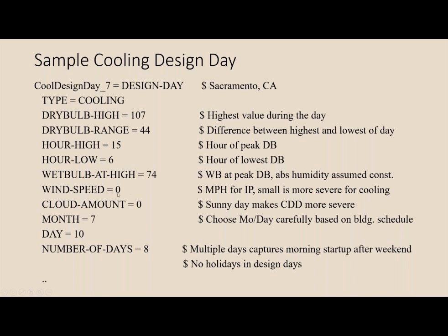I had a fairly high wind speed in my design day, and I discovered that during the design calculation the wind was cooling off the building envelope, and I was getting higher loads during my actual annual weather calculations because the wind speed was lower for certain times when the outdoor dry bulb was quite high. So that's an example where you might put in mean coincident wind, or you might just want to set wind to 0 to make sure that you're reasonably conservative for wind.